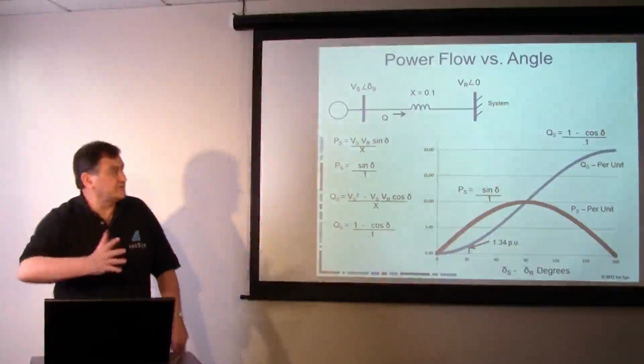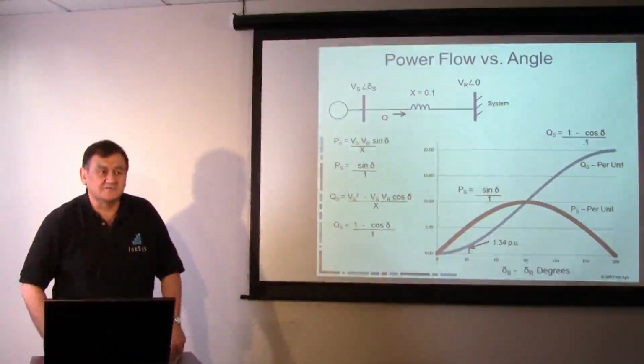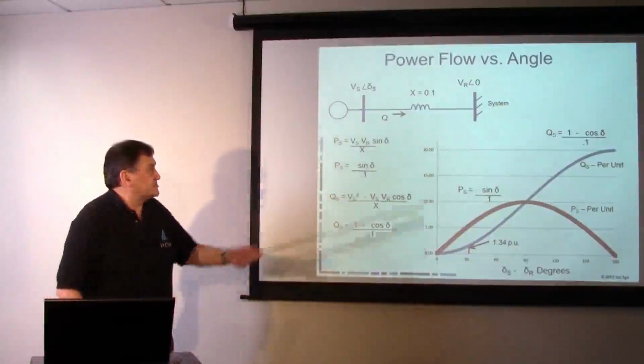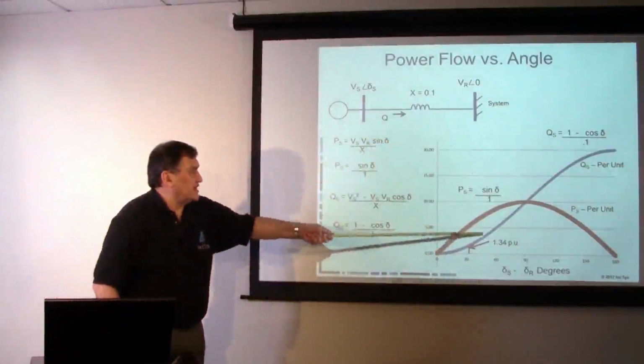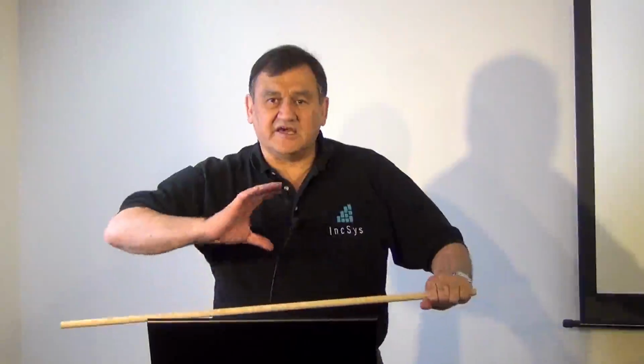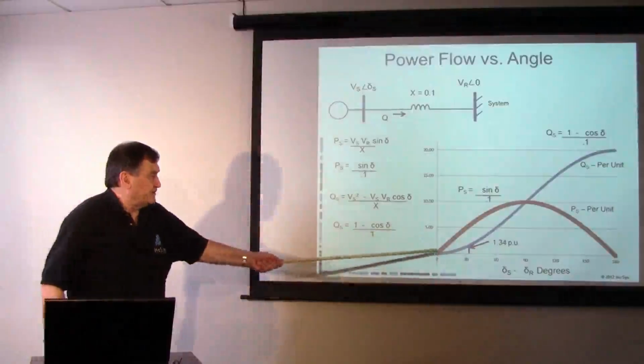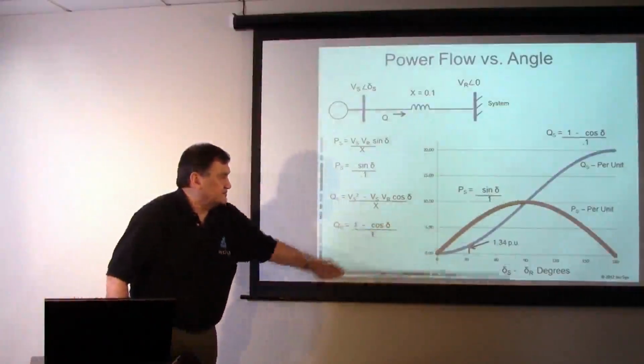We'll get into that whole thing with what we call the surge impedance loading. But this is really related to what can happen, especially as we get into what we call stability, and we get into the point where generators are oscillating and you're getting surges of power throughout the system. It's very important to understand these characteristics. So even if we don't go through all the math, I want you all to understand the basic characteristic of how the power flows versus angle.